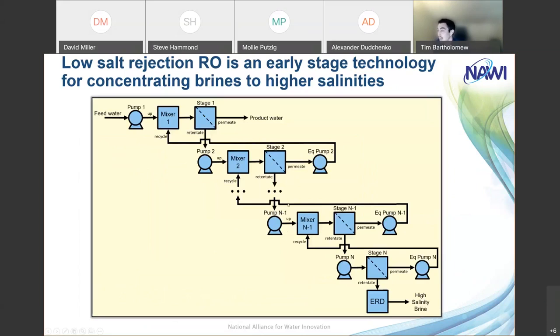Here is an n-stage LSRO process. As you can see, mostly you do an RO process at the front, and then it feeds into an LSRO process where the permeate is recycled back to the previous stage, and it just steps down from that. One of the things that's complicated about this type of multi-stage analysis is that a modular flowsheet is really useful, because the person assessing the technology can use a model library and just connect things to each other instead of creating each thing individually. So in a flowsheet, this can be rapidly assembled.